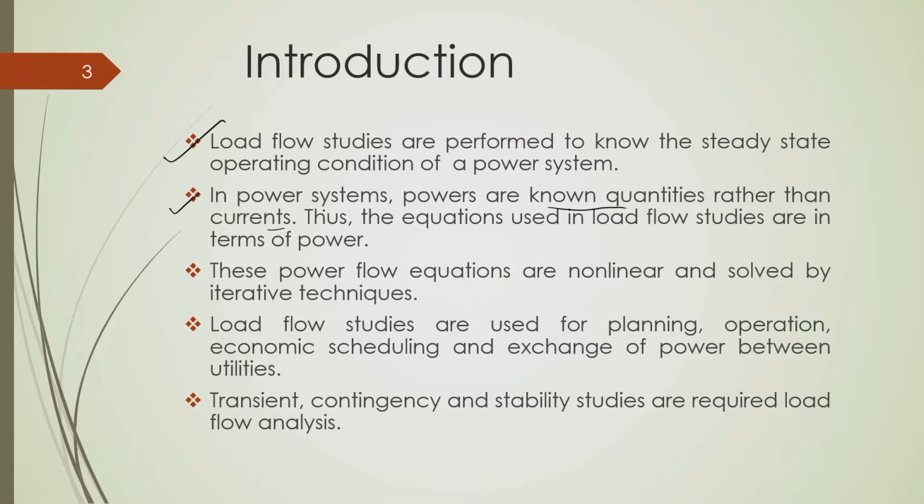So, the equations in load flow studies are in terms of power. These power flow equations are usually nonlinear and solved by iterative techniques, and we know that many power flow algorithms exist for power system load flow studies, for example, Gauss Seidel, Newton Raphson, fast decoupled, etcetera. Those are taught in the electrical power system course.